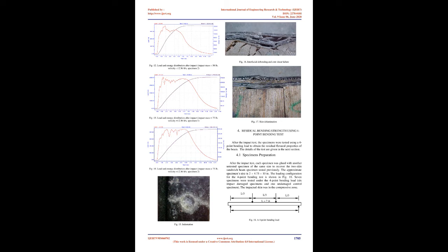The laminated skin was the front surface that was directly impacted and the half core was used as a support to the skin. It is believed that the impact damage to this type of specimens would be larger than the actual specimens, which have the whole thickness of the core and the bottom skin to provide a stronger support to the front skin. Due to the limitation of the available virgin portions from the previous full-scale beam tests, only 2 specimens were prepared and tested for each hammer weight.